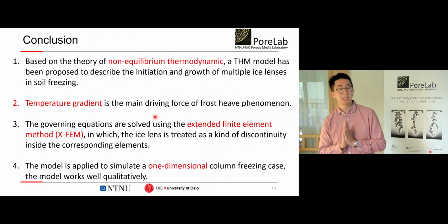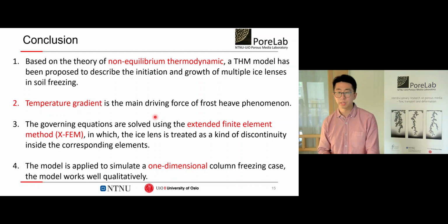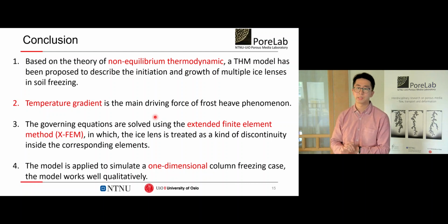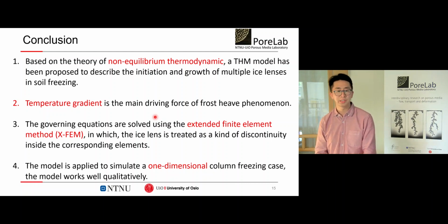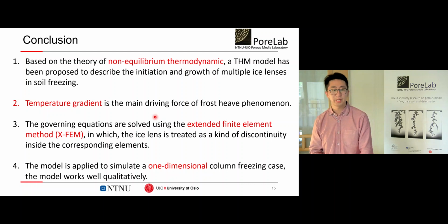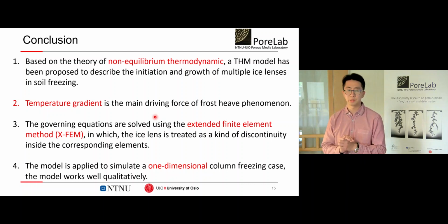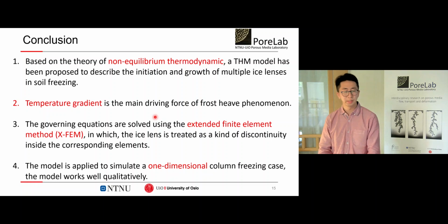Now to summarize my talk today, here is the conclusion. Based on the theory of non-equilibrium thermodynamics, a THM model has been proposed to describe the initiation and growth of multiple ice lenses in soil freezing. The temperature gradient is the main driving force of the frost-heave phenomenon. The governing equations are solved using XFEM, in which the ice lenses are treated as a kind of discontinuity inside the corresponding elements. And the last one, the model is applied to simulate a one-dimensional column freezing case. The model works well quantitatively.